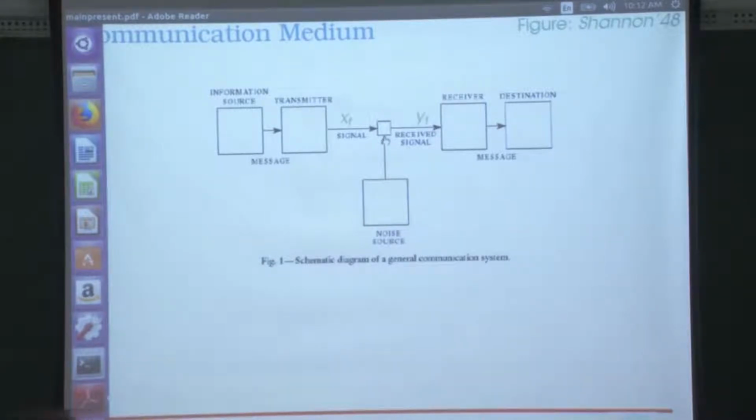So, what he did was to model that, he took that telephone line and he imagined that, look, I have to send discrete messages from this side to discrete messages on this side. So, I have some continuous signals available to me, x(t) is sent, y(t) is received. So, this is the analog part. So, I have to push data through this analog part. So, he said, okay, let me take a very natural discretization, let me just sample the signals and come up with a discrete model and try to see how much data I can push from this side to this side. So, what is the rate of communication through this particular channel under discretization?